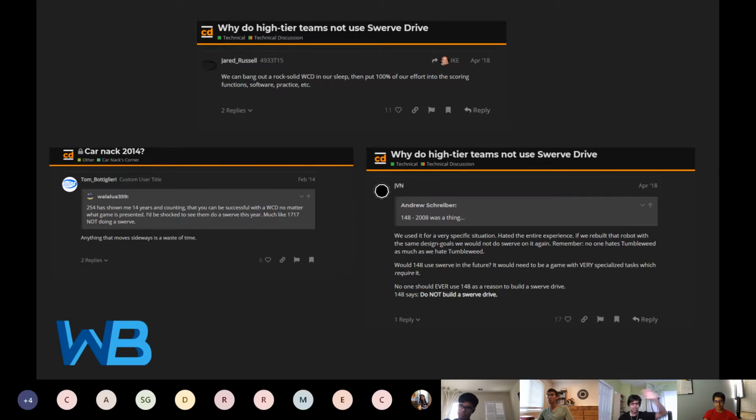Because as Sadesh said earlier, strategic design is you want to think of a strategy or an approach to how you're going to meet your goals in competition, right? And for most teams, the West Coast Drive meets all of their strategic goals. It can drive place to place. It's extremely reliable. It can move fast or slow if you have a shifter, for example. It basically provides a lot of flexibility. It uses up fewer motors, so you can spend more time on manipulators, which is why that phrase, anything that moves sideways is a waste of time, became a thing.